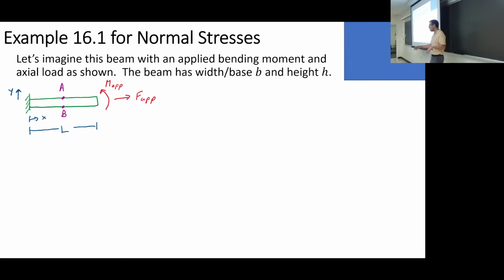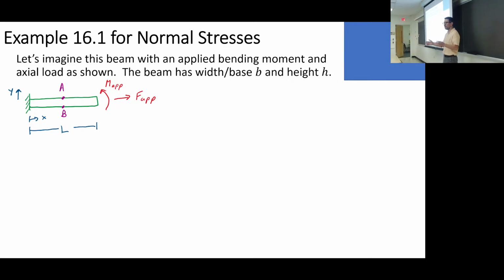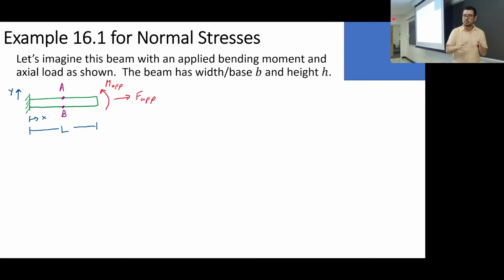Just imagine I take my table and put it in a 40 degrees Celsius room, so we change the temperature by 20 degrees. Is there still compressive stress on those legs? Absolutely. So maybe it was mean, but there's still going to be compressive stress, and it hasn't changed. Jumbo the elephant may have moved up a little bit, but I didn't push him into the ceiling, so he can't add any more. Just because the strain is zero doesn't mean the compressive stress is zero.